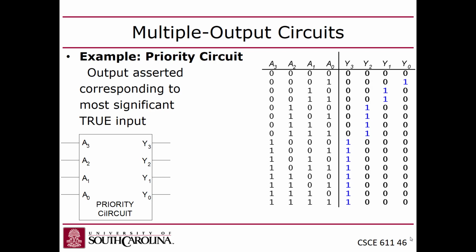The idea is that you're calculating separate results, separate outputs from the same set of inputs. You guys with me? So what's happening is that these 4 inputs come in, and some of them are going to be fanned out, split off and connected to different gates, which ultimately may be generating different outputs downstream, down the line. You guys with me?